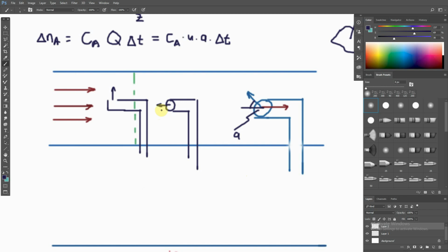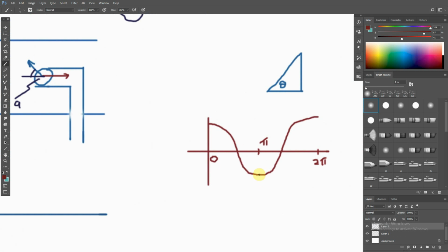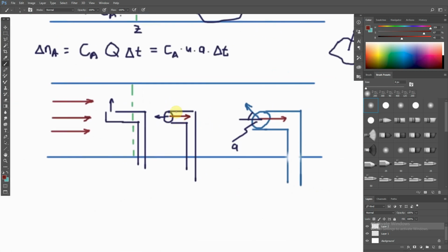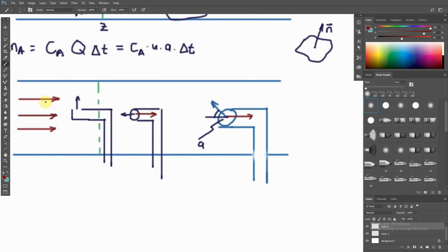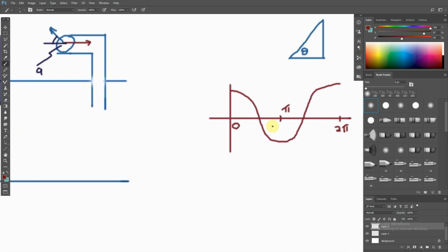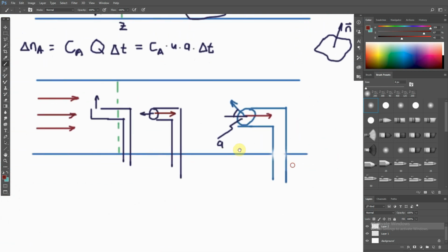Now we can see here that in the earlier case, let's take this case, your unit normal outward vector is like that, and your velocity is like that. So here the angle is 180 degrees, or pi, and so the cos of pi is -1. So we've got -1 times the area, so we still have a high flow rate. As you increase the angle, and once the angle gets to 90 degrees, which is pi by 2, you can see the flux through is 0. So in terms of flux, which is directional, you have a dot product relationship between the velocity and the area.